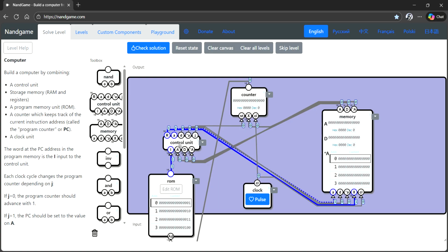Because this part is bigger and this part is smaller, this part will take more time, this part will take less time. So when you combine them, in a particular amount of time, this is still calculating, but this has given its output. So when you assemble them, the answer will come out to be different because they are out of sync. So to sync them, we introduce a clock pulse.